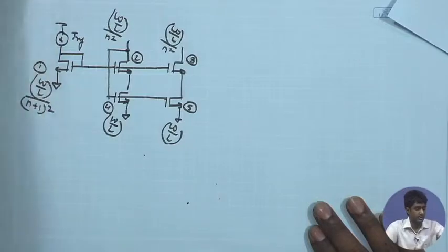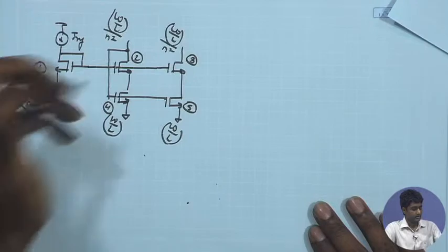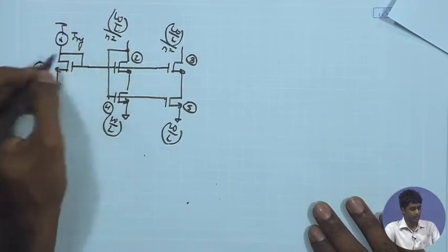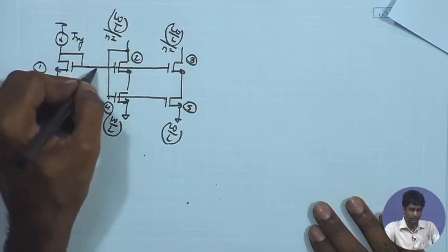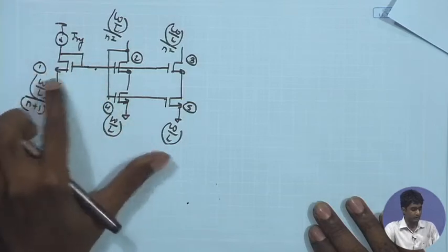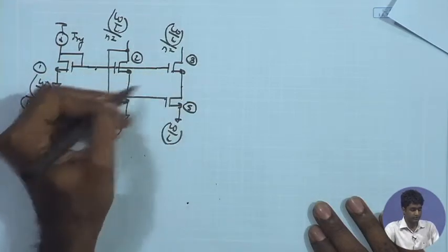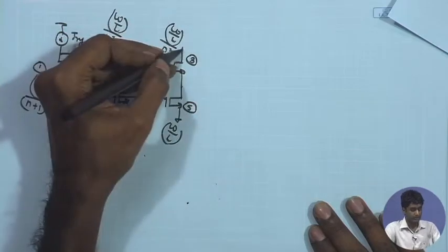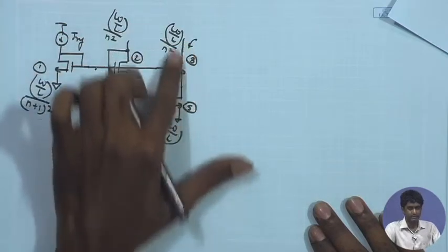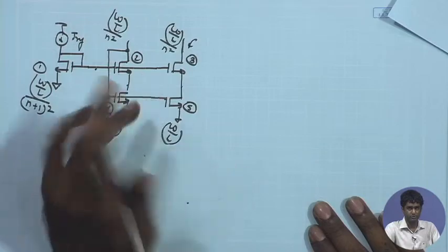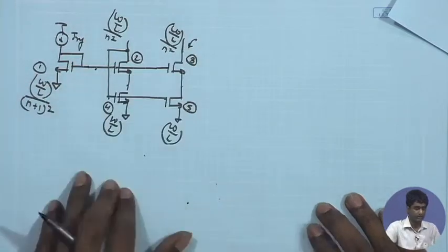And as a result, I have to look at the DC gate voltage generated over here with respect to the reference current, and also look at the DC potentials at these two points, and figure out, if this is my output branch, which is biased with respect to these potentials, what is the minimum allowed potential over here.